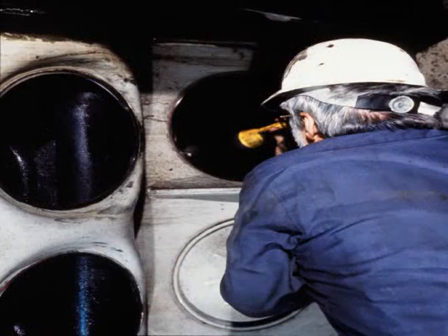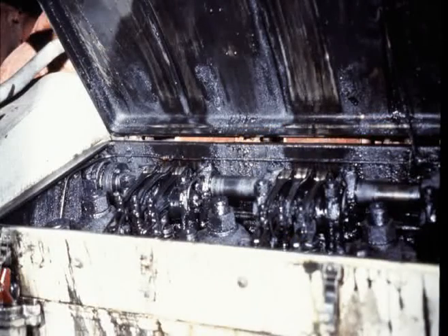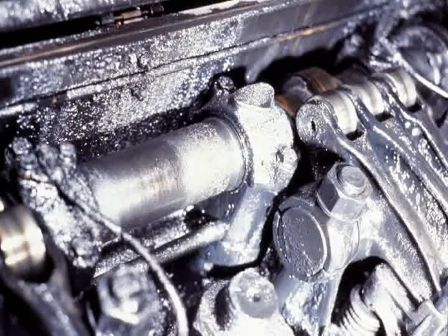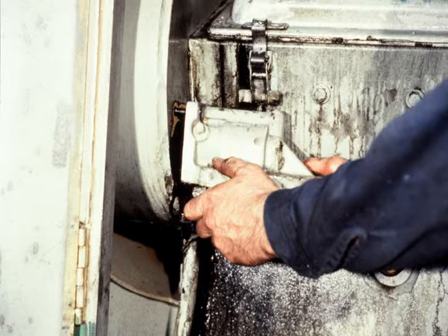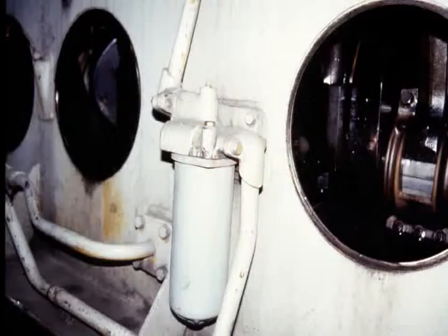The soak-back system can be qualified by energizing the fuel pump and removing the number 16 crankcase cover and looking up into the rear gear train to observe oil returning to the oil pan sump. If no oil is detected, then look at the camshafts on the right rear section of the engine. If any oil is seen from the cam bearings or rocker arms, the large check valve in the turbo filter head is leaking and must be repaired. If no oil is seen at either location, the problem is likely in the soak-back filter.